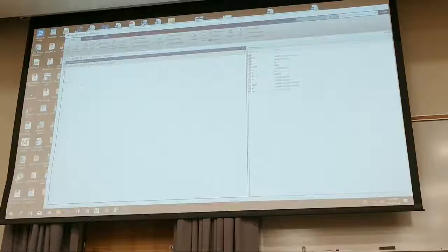It's a matrix thing. If I want a 2x2 matrix, and I want it to say 1, 2, that's the first row. A semicolon brings it to the second row, and I'm going to have 3, 4. You'll notice I'm using these actual brackets, not curly brackets or parentheses here. When I look at that, 1, 2, 3, 4, the columns are 1, 3, and 2, 4. If you wanted the transpose of that, this is the transpose. The columns and rows are reversed. You know what a transpose is from your linear algebra, right?